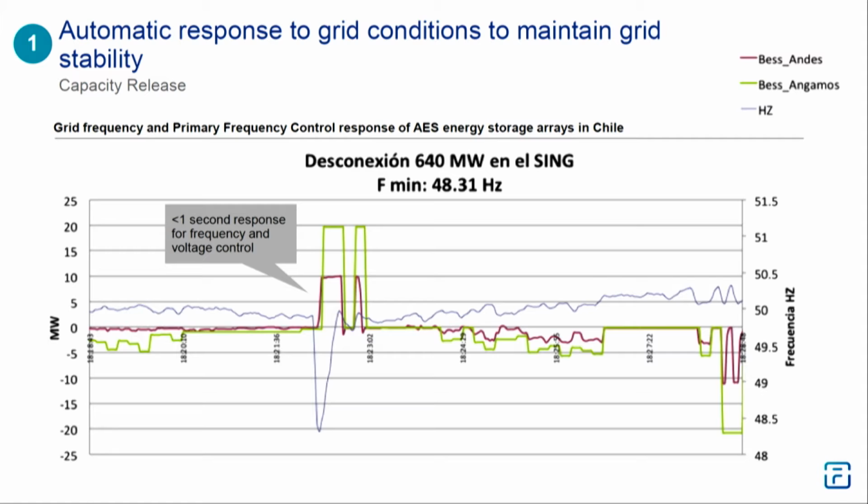So in the first case, what we refer to as N-1 capacity release, this is really the case where you have existing steel or copper in the ground today that's just not being utilized. So citizens of Ohio have paid for that through their rates. In many cases, in some places in the transmission network in particular, there are links which have an operational cap set upon them, that has nothing to do with their thermal capacity. Because if we put too much power through that transmission line, for example, in the case of a contingency, that line trips offline, it could threaten the stability of the rest of the network. So say you've got a 2,000 megawatt line, we operate it at 1,000 megawatts to avoid that contingency issue.